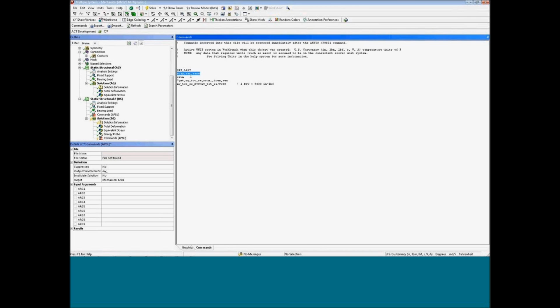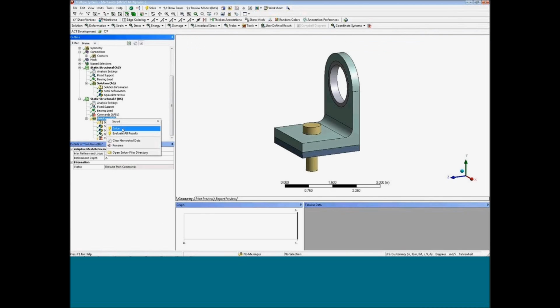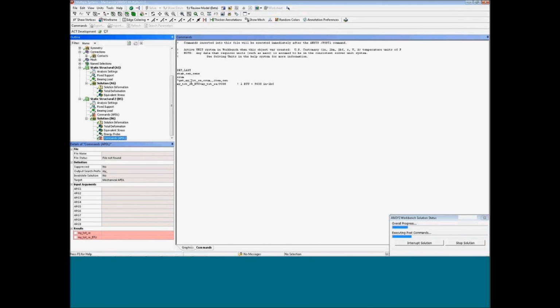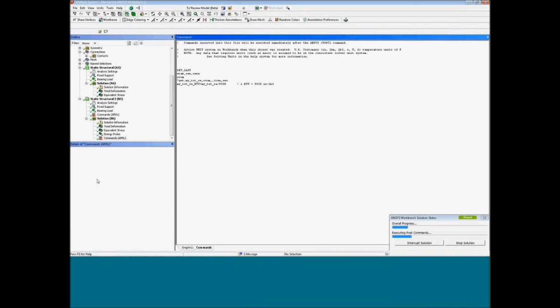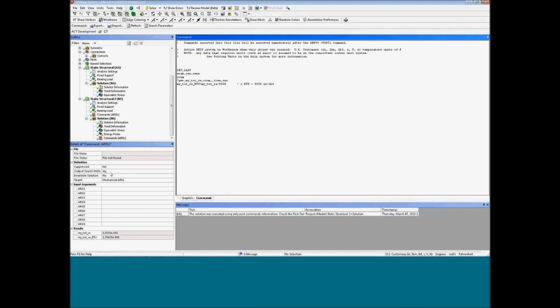I just element table all the elements for strain energy. I sum up that element table, get the summation from that, and store that as a parameter here. I'm just going to evaluate this while I talk. I set up this parameter name specifically with my underscore as the prefix, because if you notice in the details of this command block, there's a search output, my underscore. As long as we set up whatever the prefix is in here and make our parameters match, those will show up in the results down here. So you can see the values of those show up in here. And you could check this box and make a parameter out of that. I'll come back to that at the end of the webinar.